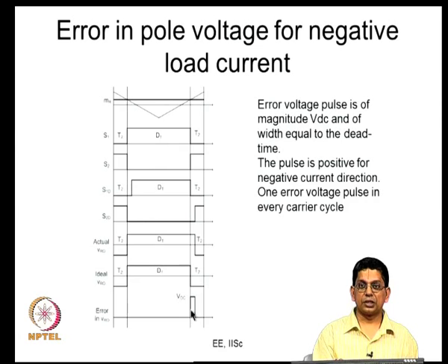Dead time is necessary. What is that? The switches take a finite amount of time to turn off and turn on. So, when you are switching complementary devices, you must first turn off the outgoing device, and then turn on the incoming device. The incoming device should be gated high only after some finite interval of time, which is called dead time Td, and this Td has got to be significantly higher than the worst case device transition time.